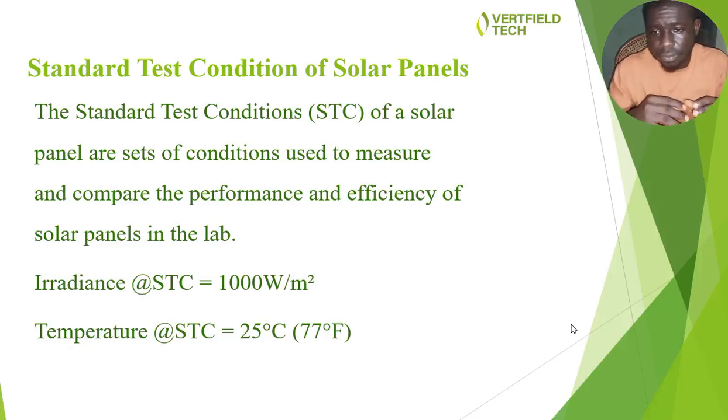Now, one of the basic reasons why you are asked to use solar accessories in terms of the solar rails when you are installing your solar panels on the roof, you are advised never to install your solar panels directly on the roof. On no account should you install your solar panels directly on the roof. This is to allow for cooling of your solar panels.